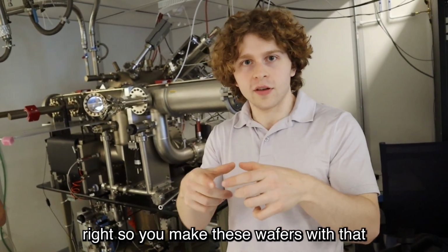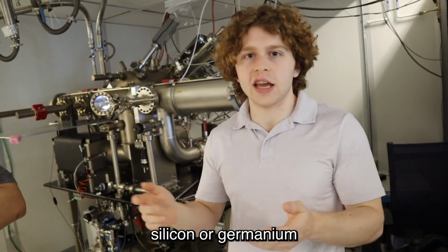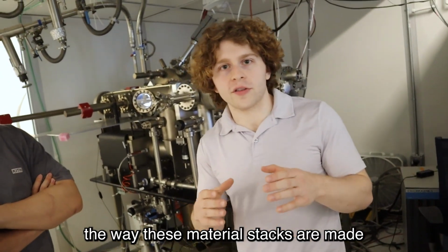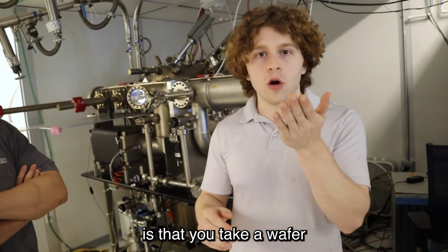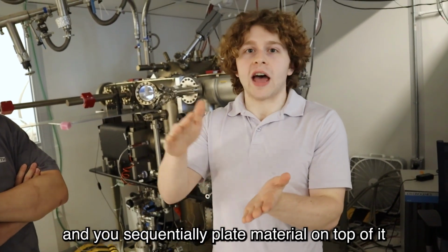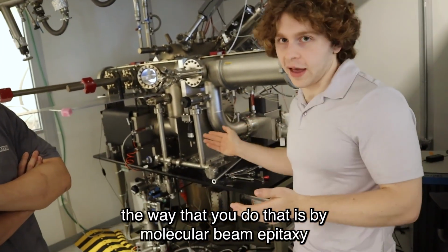So you make these wafers that have silicon or germanium or whatever you use in a computer chip. The way these material stacks are made is that you take a wafer, which is a substrate, and you sequentially plate material on top of it, right? And so the way that you do that is by molecular beam epitaxy.